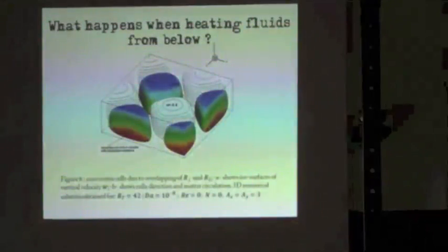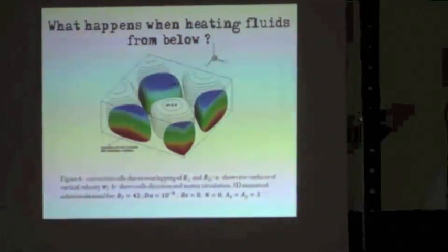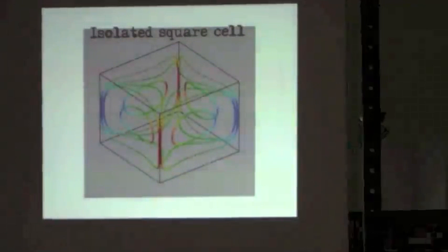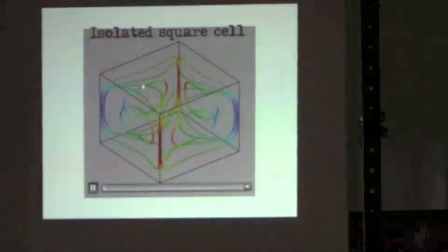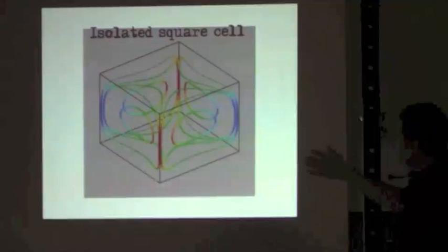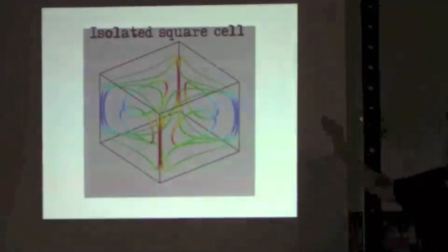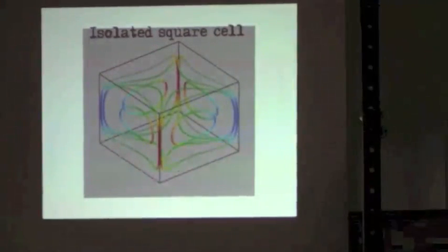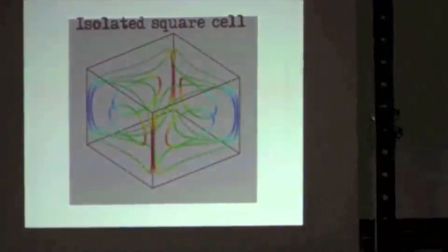Here we show the isosurface of W speed. Clearly we have an oblique structure of convection. Here we isolate one structure. The important information is that this motion is stationary. For natural convection, and for one pure liquid, the convection is stationary.